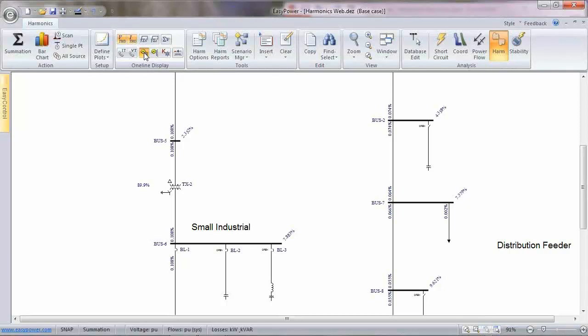We all know that. It doesn't matter if you harmonically overheat it or if you fundamentally overheat it. If it gets hot, it starts to lose its life and create damage. So the harmonic currents through the transformer are basically giving us a condition where we can't put any more than roughly 90% through this transformer. What's the K factor for the same thing? 1.9. And that's how you display it. All you have to do is click on transformer K factor up here, according to UL 1561. So there you go. Derating, K factor.